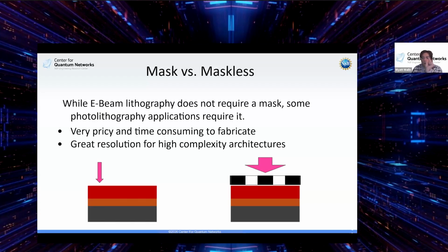Maskless is simply we're gonna take this beam or this UV exposure, and instead of making it as big as a lamp, like a big UV exposure system that will just send photons down, do the interactions, yada yada, instead, it will take this laser and move it down to a small write head, and then it will slowly write across the surface.